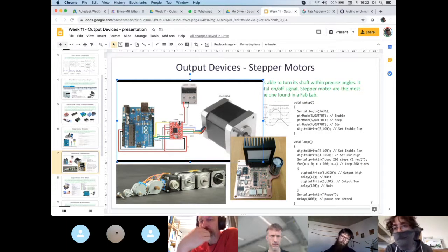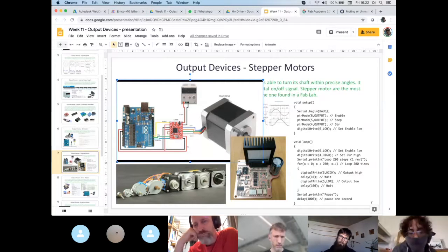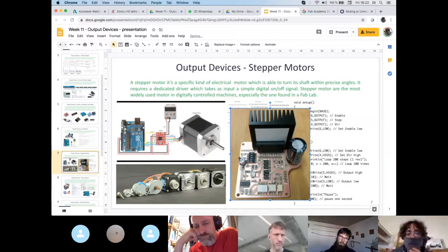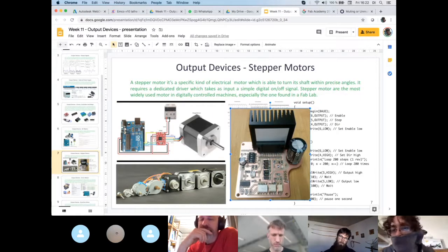So these big caps act as a buffer, accumulating the charge needed to boost the start of the motor every time. Of course, the bigger the driver, the bigger the capacitor. You also have other caps, but they are for stabilization of the voltage, for example, of the motor. The one for stabilization is much smaller than the one for giving the boost to the motor.